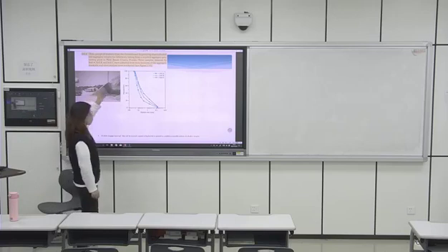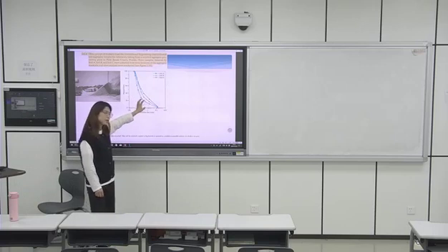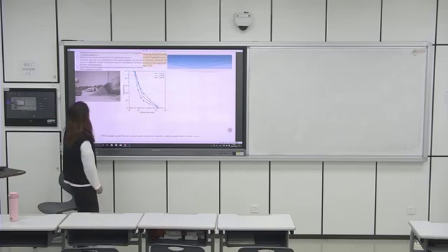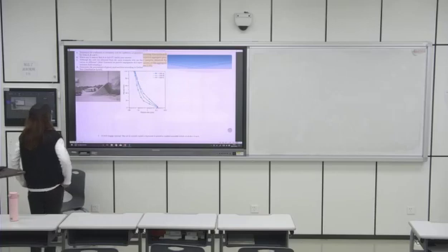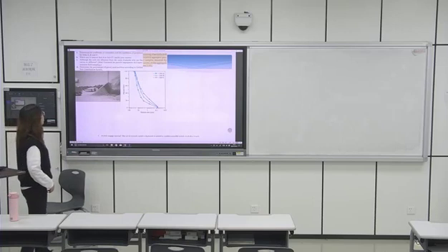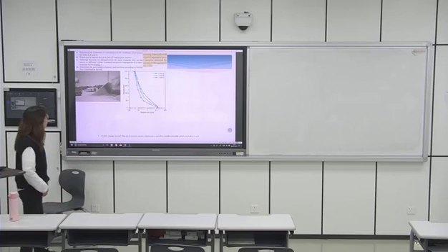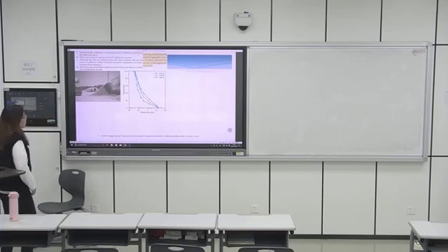So the three different students got the samples from those piles, and then did the sieve analysis and got the particle size distribution. It's like this. It asks you first to determine the coefficient of uniformity and coefficient of gradation for soil A, B, and C. That is Cc and Cu for soil A, B, and C. And then, based on Cc and Cu, it asks which one is closer, soil A or soil C, and to justify your answer.